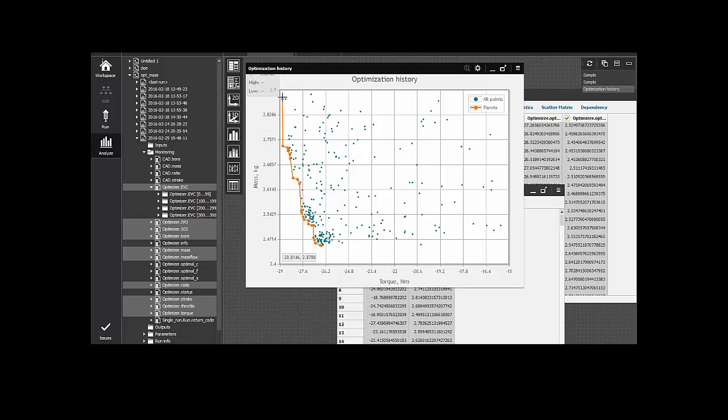So it's kind of a tool for trade-off study, to study the possibilities, and we get this Pareto frontier with quite high resolution in only 300 evaluations. That's the way you solve the optimization problem in pSeven, and how you can plot the results to analyze them. It's one of the graphs available.